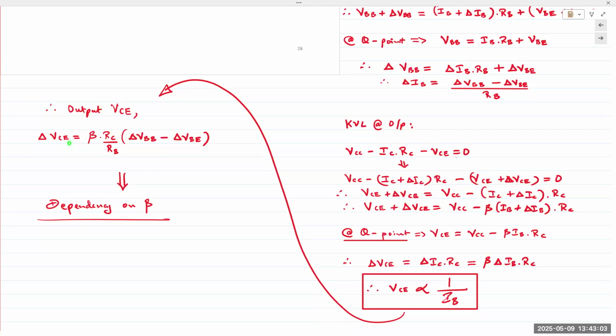Well, if it's 35 and 200, your design may not work, right? This is a very simplistic design with the bare minimum of components. We only have two resistors on either side to bias or control our current. So there are lots of quantities in there that we have to account for. Any variation in beta is going to result in a very large variation in amplification, and instead of operating in the active region, your transistor would be operating either in cutoff or in saturation, and you'd have a distorted output.